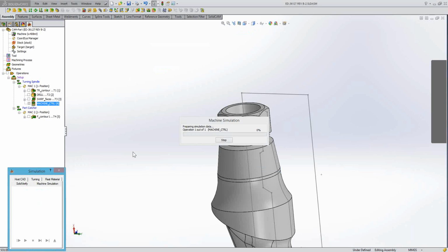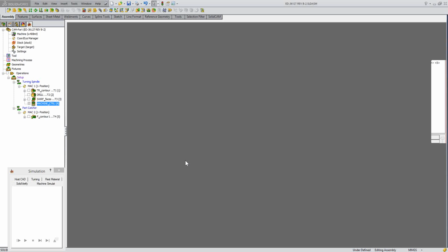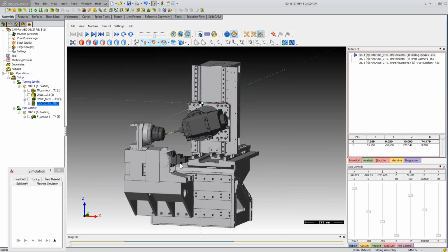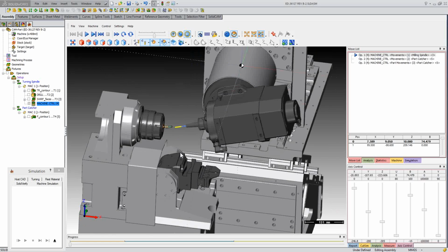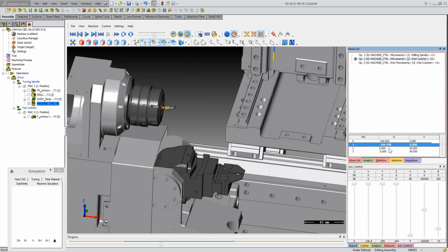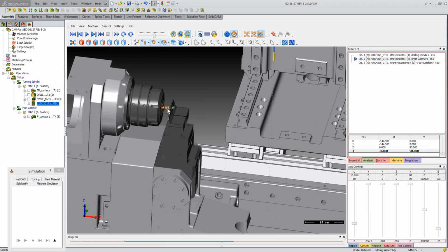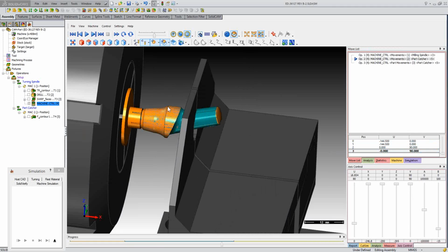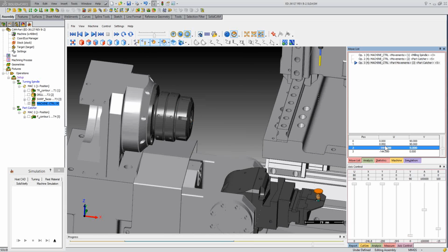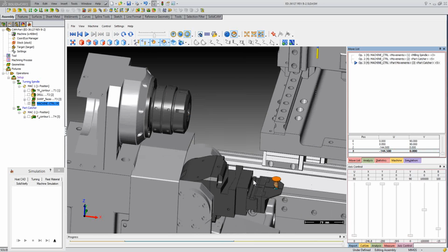SolidCAM will ignore what I defined in the setup. Using MCO, part move, will ignore what we define in the setup and use the new values, because I have the right to change my mind. Okay, take it from here, -10 I am now, not on -17 millimeter. I'm catching the part in a different position. It's my right. And continue to work.